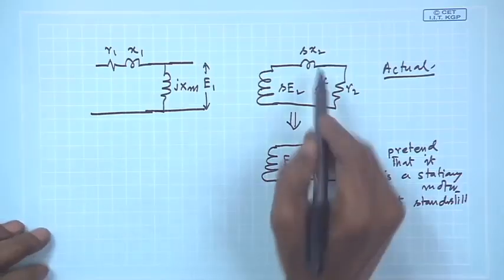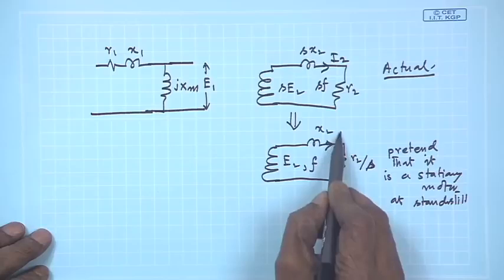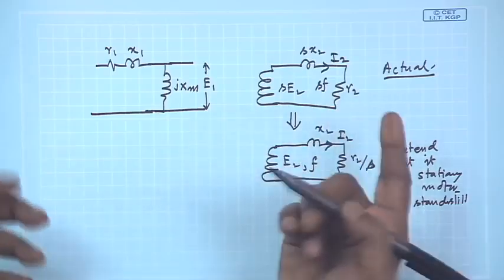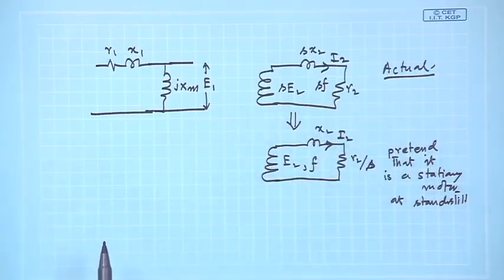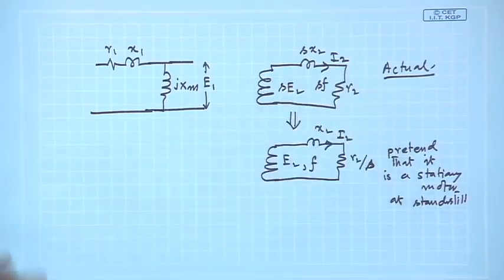Okay. This is the I2 RMS value, this is the I2 RMS value, which means its maximum value is also fixed, and the maximum value of the current has to decide what will be the strength of the corresponding rotating field. It is 3 by 2 B max. So, if you keep the RMS current constant, it is the same.